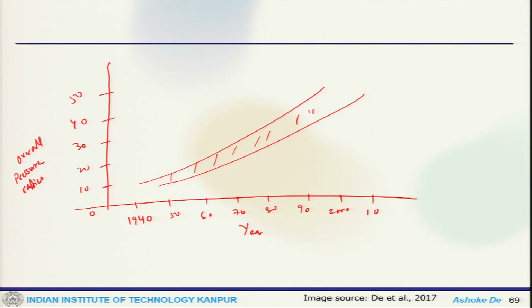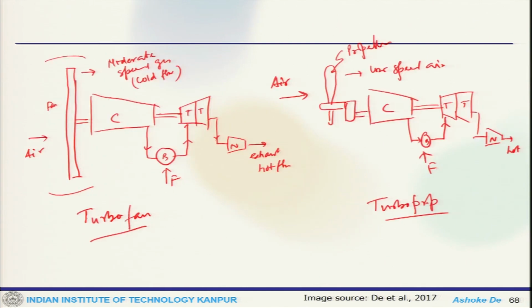These engines, both civilian aircraft and fighter aircraft, use a sort of turbofan engine, but of different categories. In your turbofan, there is a portion of the air which goes out of the core, and a portion of the air which comes through the core of the engine. If this is the cold flow and this is the hot air, the ratio is the bypass ratio, that is the percentage of the cold flow of the total.